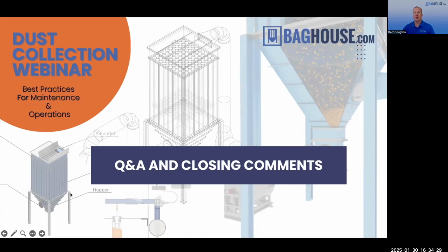It's very simple. I understand not every customer can do that. Sometimes if you're recycling the dust out of the hopper and it's going into your product, you may need to look closely and see if that'll work for you. But for most people, they can. Basically, you just take this powder, which is colored powder. It shows up under UV light. So you suck it into your bag house. You can introduce it through the upstream ductwork and let it coat your filters. Let it run for a few minutes, then you shut your system off.